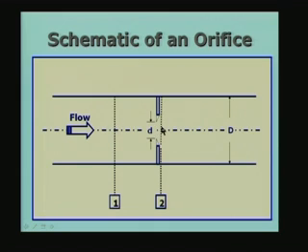Now, we can choose two locations, 1 and 2. In this case, I have taken one upstream of the orifice, usually 1 diameter away from the orifice, ahead of the orifice, and the second one I can choose very close to the orifice, like what I have done. There are different ways of doing it, which we will come to a little later on.